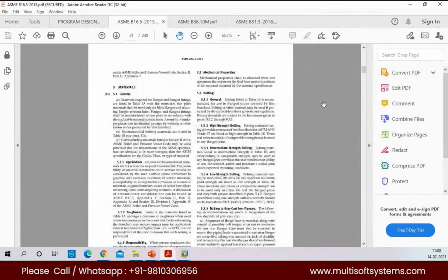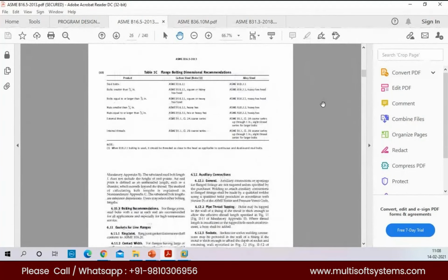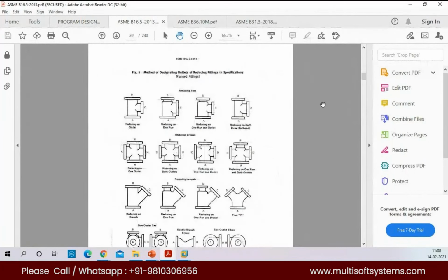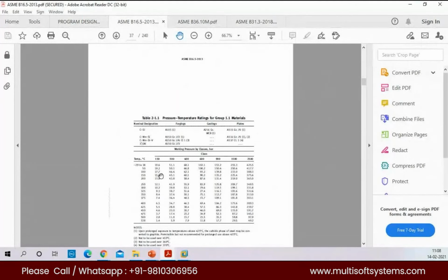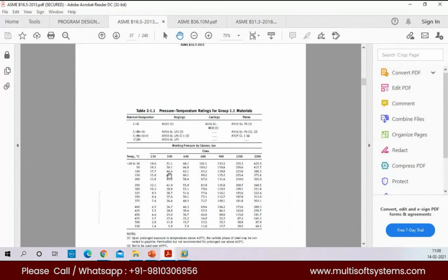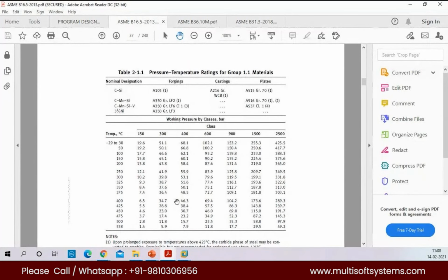We have to check whether the flange, all the fittings, everything satisfies that or not. The pipe material, the flange material, everything has to be taken care of. So here also there is a limit. The rating also will be different based on the temperature. That means, exactly as a process layout person, you have to tell me, because that selection has to be made by the process engineers.